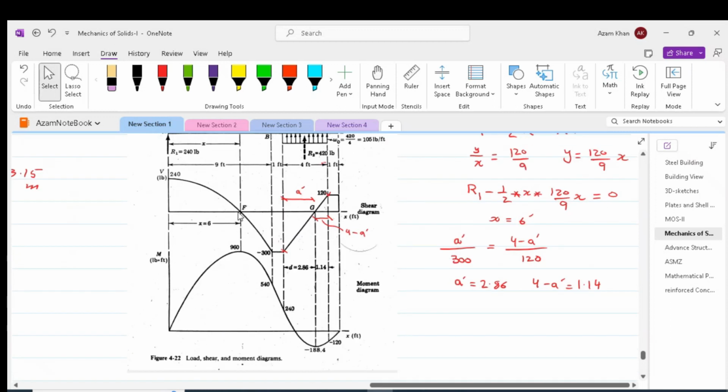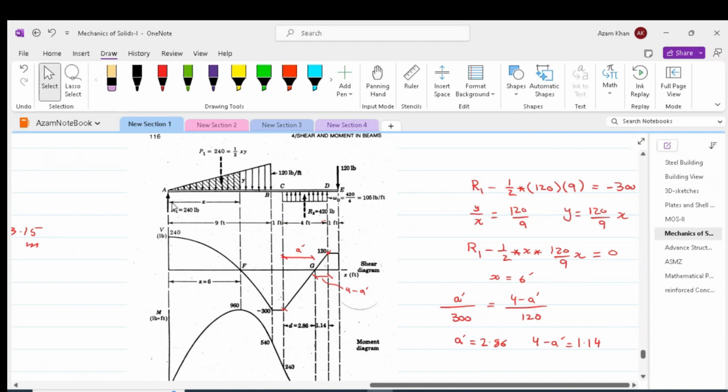So again, at the point of 0 shears, we would have maximum moments. And the reason is that we have these shears appearing between the concentrated loads. The reason I say that we would have maximum moment at zero shear, provided the shear is in between the concentrated loads, is that in the case of cantilever beams, the point where we have maximum shear would have probably the maximum moment. It's only in the case of simple supports that we can have a case where at the point of zero shear, we would be having maximum moment.